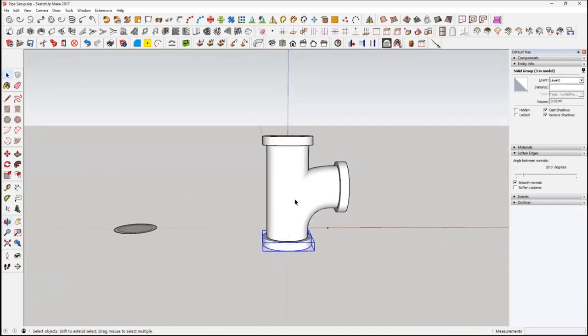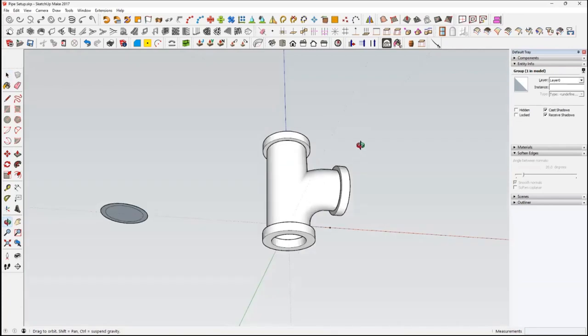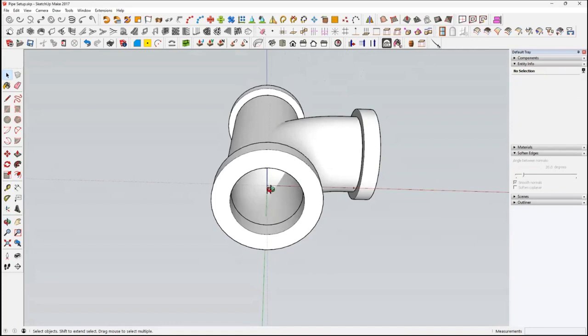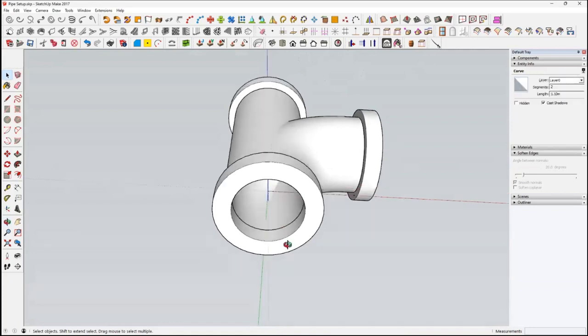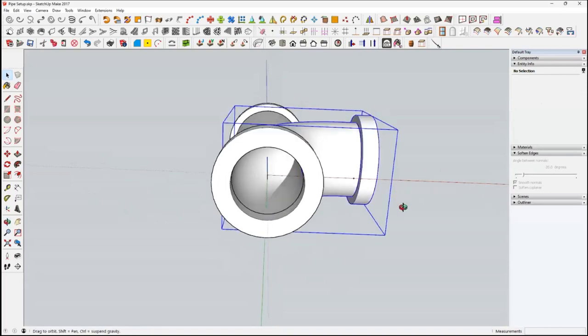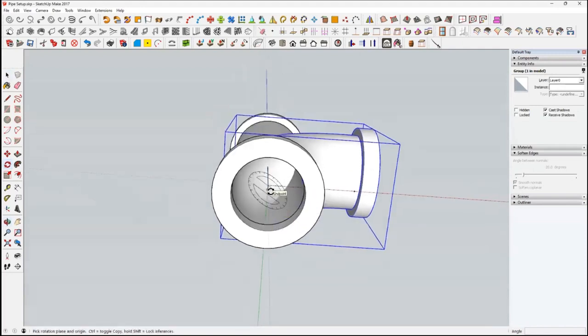And what you can do is click on the right angle and then click on the collar. And then in 2 bits, right click and make it a group. So now what you can do is come in the bottom. We've got our line that we drew from earlier, which we know is dead straight up the middle. So if you come with a protractor tool, actually first thing we'll click on that collar and an elbow and the sweep there. Go on the protractor tool, find that line and put your protractor on it and press the blue, which is the up arrow.